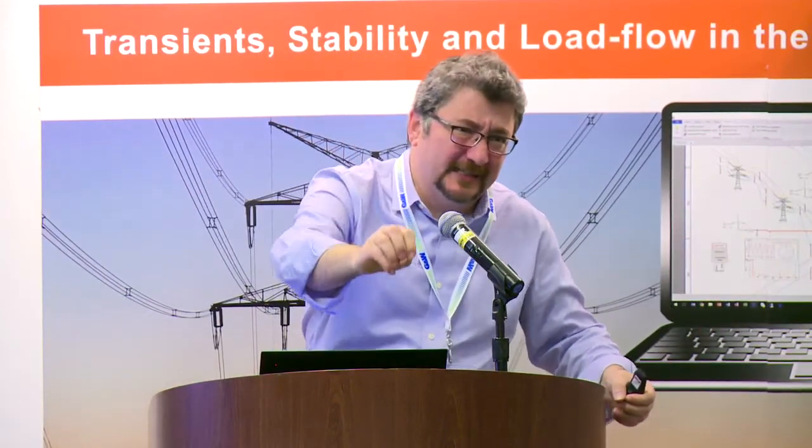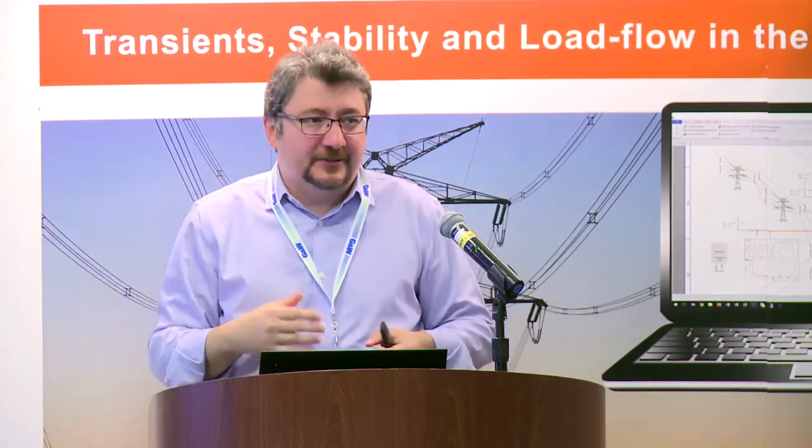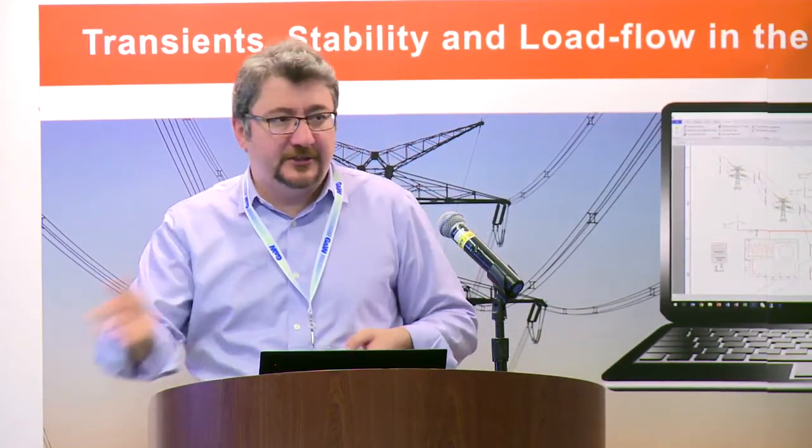If there is a problem, you can say, okay, it's a short line, maybe I increase the frequency band, and since I increase the frequency band, it's a good idea to apply DC correction as well, so partition the band and so on. These are particularly for short cables and lines. Otherwise, if you have a 50-kilometer line, I don't think you'll ever need it. The default parameters will just work. I mean, this is for 98% of the cases.